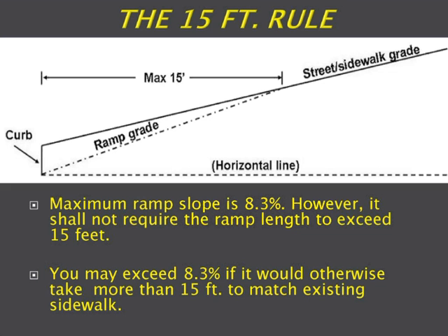But one of the things that I caution is that if it's close, if you have to go maybe 20 feet or 25 feet to get the 8.33%, I think it's worthwhile to go a little further. That's not an absolute like the maximum 8.33%. That 15 foot is an absolute. Use some judgment if you can go a little bit further, and it's practical to do so, and go a little bit further to flatten it out.